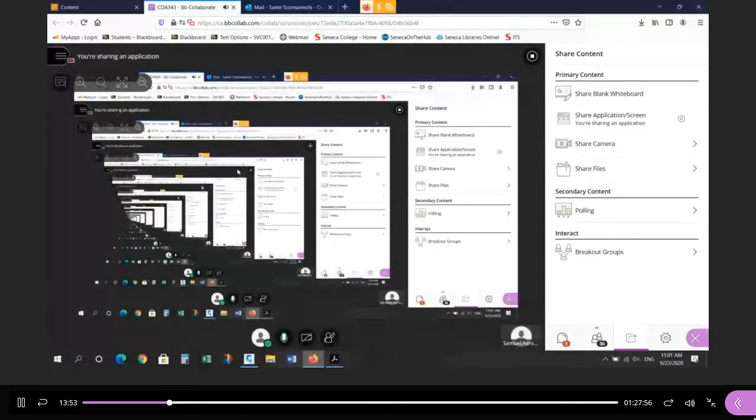There's no harm in creating the layers. It's just more work, unnecessary work. The problem is if you misspell them when you create them, then you'll get the one you created misspelled, and then the new one you get when you import. The T- layers you get for free, so don't waste your time.